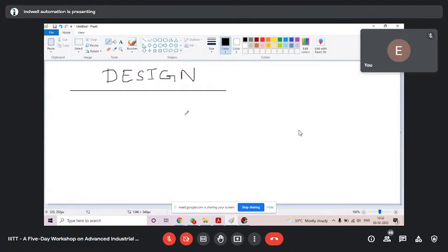So in a simple way, if you connect your three PLCs with three USB ports of your laptop, then you check in your device manager. And in SCADA, you configure each driver, mention there. Okay, Mitsubishi COM port 1, Allen Bradley 2, Siemens COM port number 3.